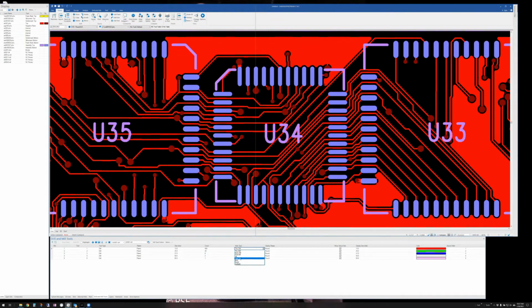In the 160, all analysis basically just runs on whatever you've got, but in the higher end, you can say, this is a laser via, so therefore I only need, say, 3 mils annular ring, or this is a mechanical via and I only need, say, 5 mil annular ring. You could have those separate in the higher end one. So just up to you again.